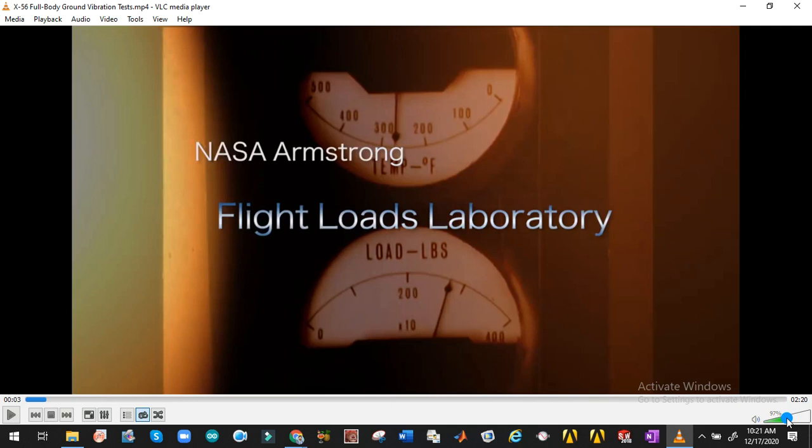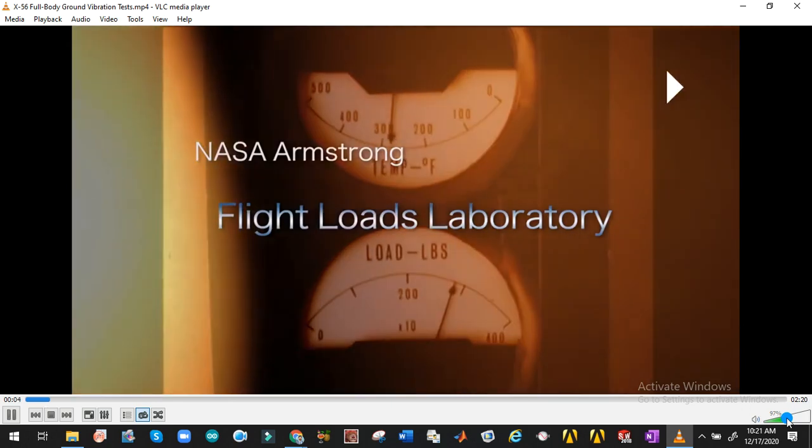There was a problem within the reciprocating compressor, and that vibration was traveling across the pipeline, and then we solved that problem by considering the mode shapes. And in that example, we also found the wavelength. So, the wavelength will let us know where to connect the vibration transducers. So, let's see that video.